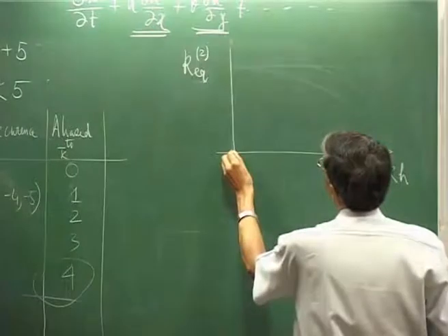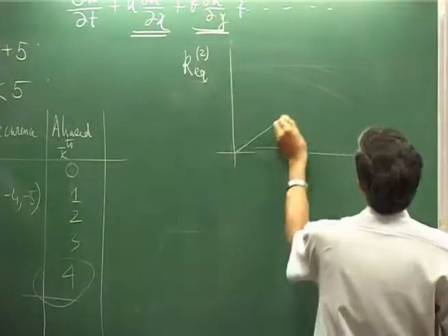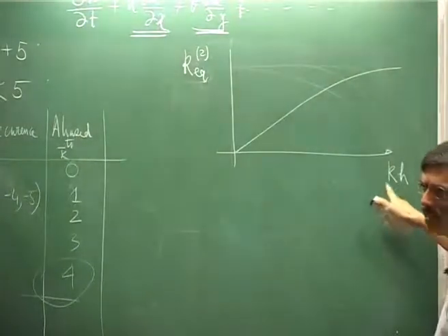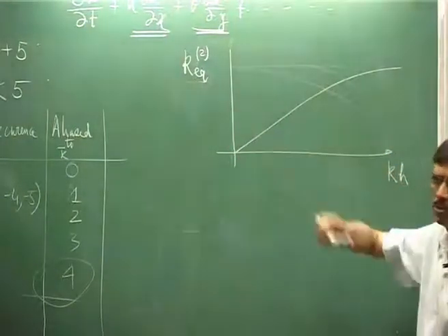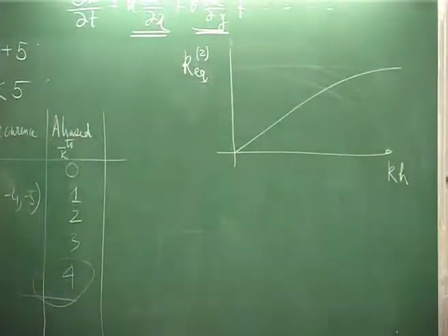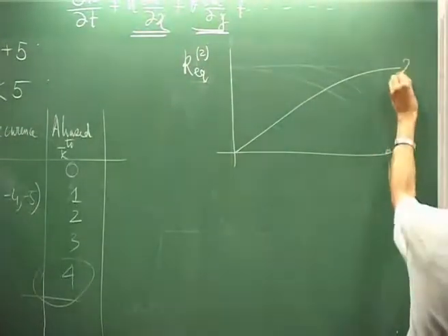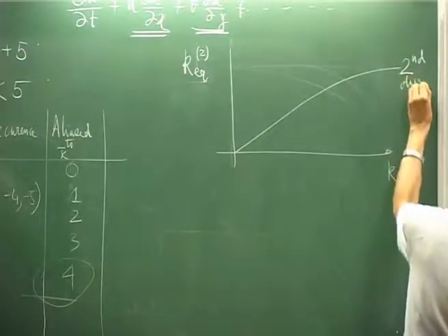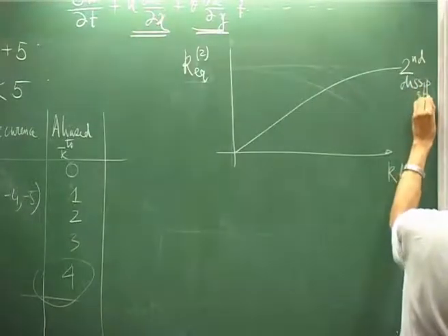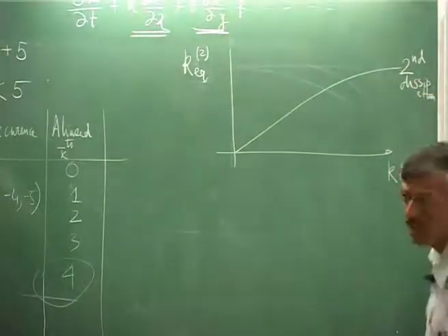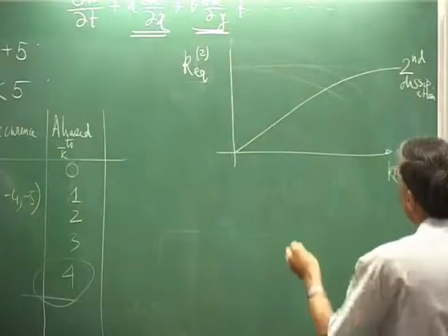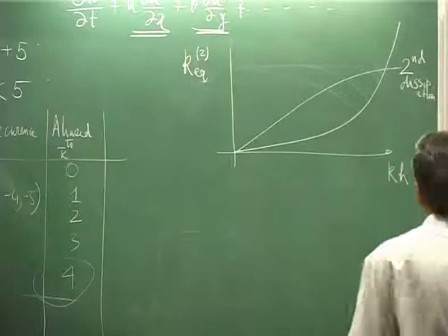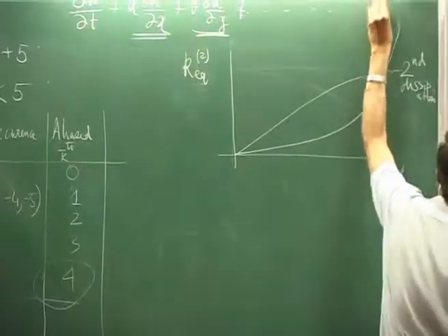You will notice that this goes like this. So as k increases, your added dissipation actually increases, right? And this is, let's say, for second dissipation. And if I add a fourth derivative term, it would behave like this. So this is your fourth dissipation term.